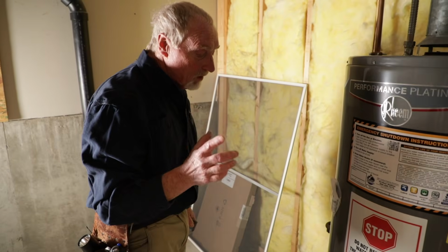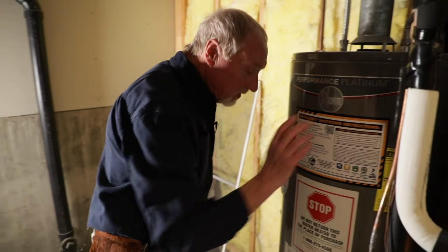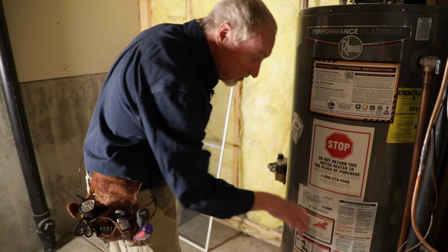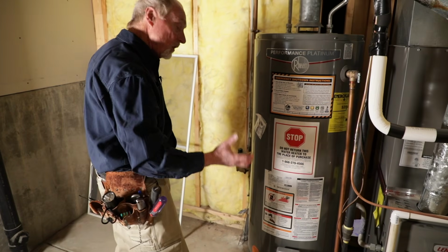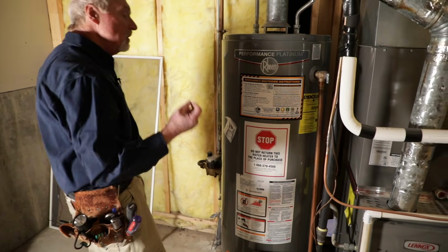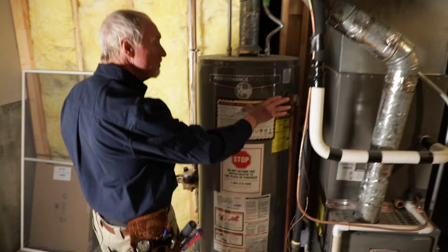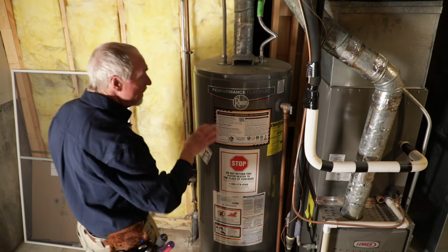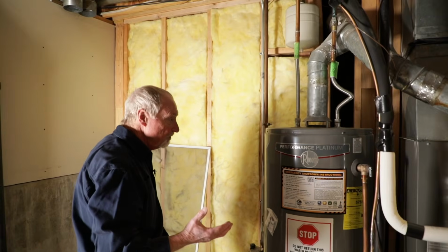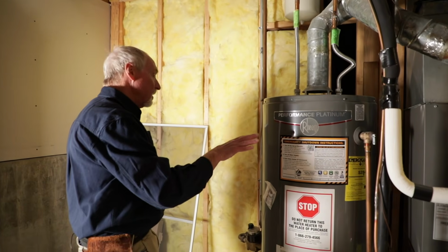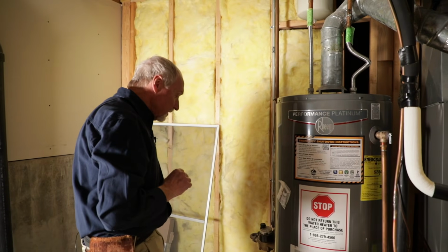And one thing to check for, whether you operate the valve or not, any evidence that water has been coming out of it in the past, with stains on the floor or anything like that, that would indicate that maybe sometimes this valve is opening, which might mean that the water heater is building too much pressure occasionally. But in this case, we're looking very good here with this one.